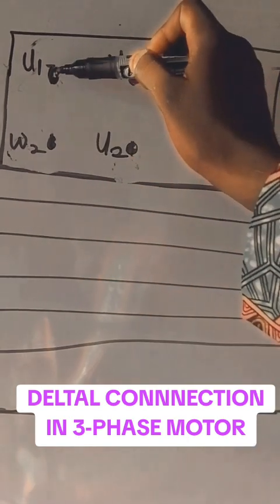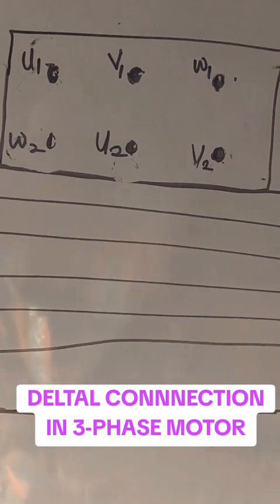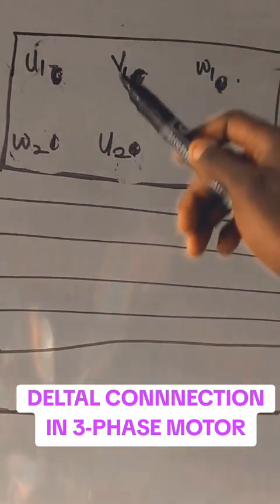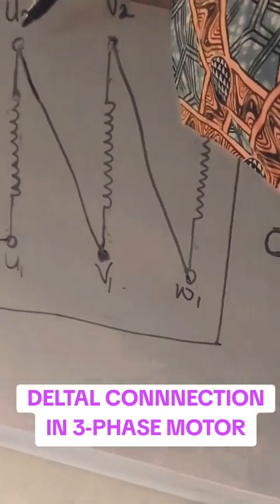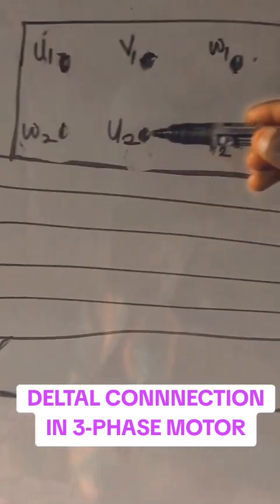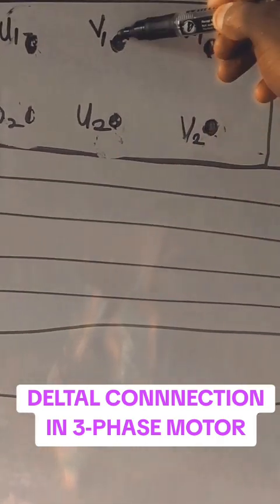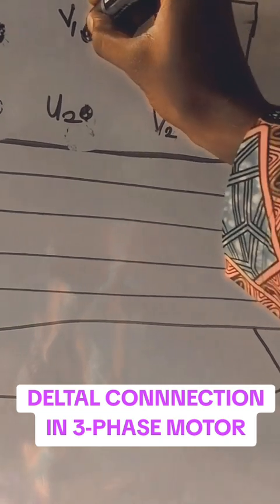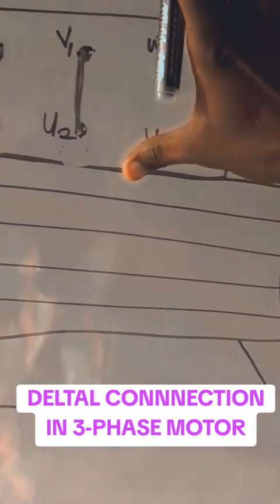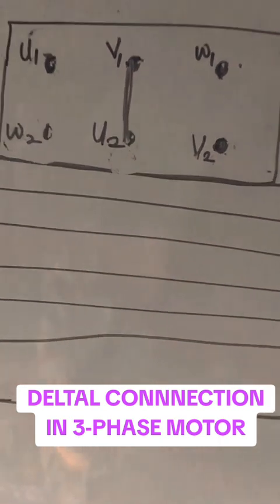If they should arrange it such that U2 is directly opposite to U1, it will make it difficult to put a jumper anytime we want to connect it in delta. So that is why they interchange the terminals, such that in this case, we have U2 linked to V1. Let's look at U2. Where's our U2? Can you see U2 here? And V1. So for me to link them, I will just put a jumper. Have you seen it? So they are directly opposite. Just a small jumper can be used to link them together in the terminal box.